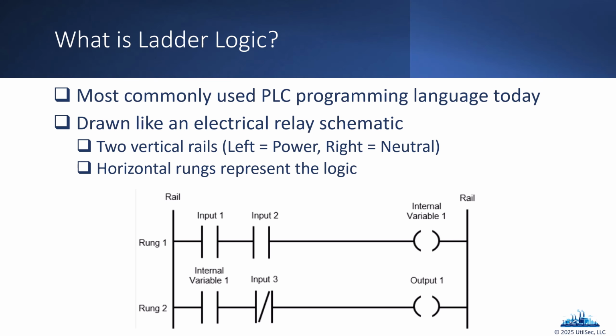And this is where I started to go down the road of talking about what is ladder logic and how we program controllers. And I realized this is already a 4-hour part of the course, now broken into 2-hour pieces. This has to be a whole other 4-hour workshop where we talk about what is ladder logic. We're simulating bringing in electricity on the left-hand side, and we read it top to bottom, left to right. And you start to see inputs and outputs, as we bring in data and send signals.